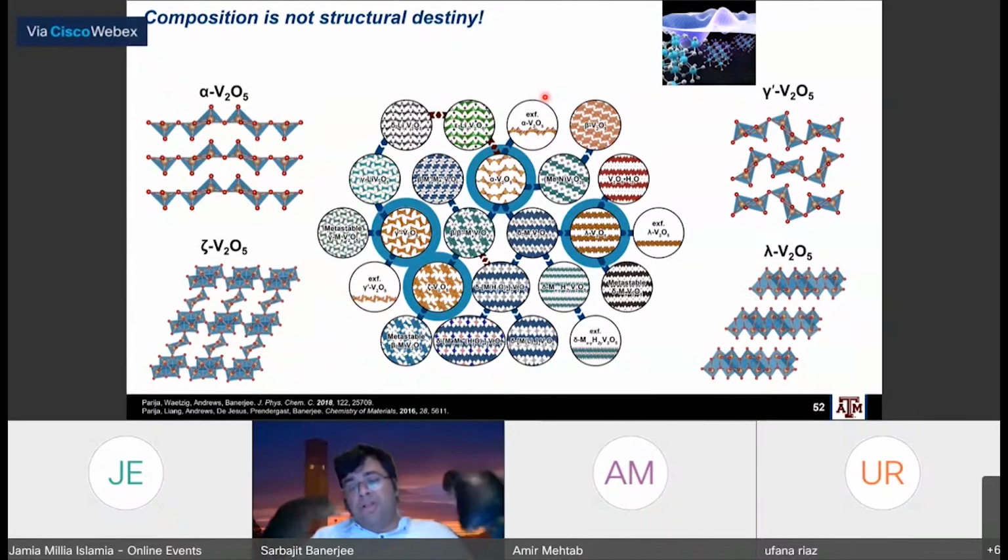Some of the problem, not all, lies with the catalyst, right? We still, I think, are struggling both on the oxygen evolution side as well as the HER side with replacing precious metal. That's a big part of the cost. But indirectly, a big part of the cost is the large stacks that are required for electrodes, and the large stacks often also come from simply the overpotential being large and the catalyst being suboptimal in performance. So you cannot just replace these with cheaper catalysts, but we need better catalysts so you can cut down on the entire stack cost.